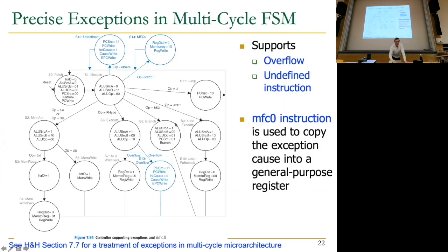So this is how the exception handler can figure out whether it's an overflow or an undefined instruction, essentially, and then it can take some action accordingly. If it's an undefined instruction, of course, you have to stop the program, right? But you may do some bookkeeping, saying that there's a particular instruction that people keep using as an undefined instruction. Who knows, right? The system can do a lot of recording, for example. Okay, so that was the example of an undefined instruction, undefined opcode exception.